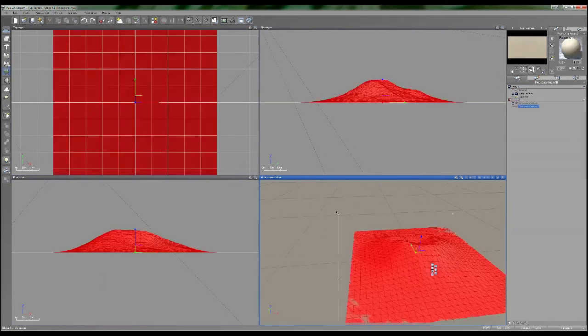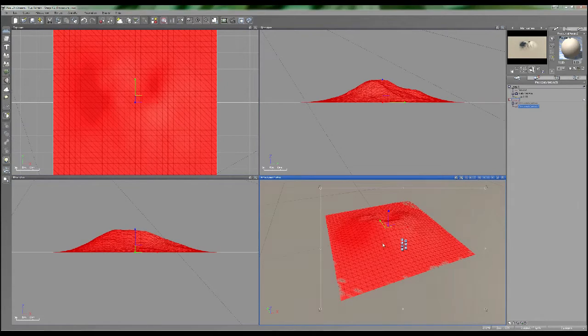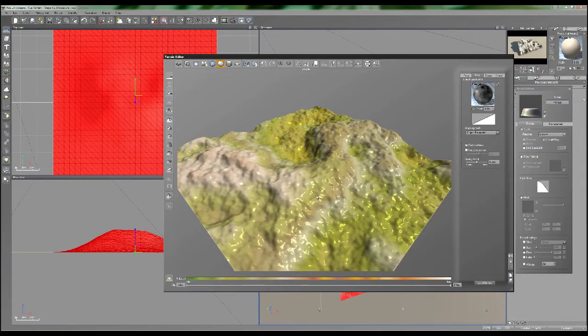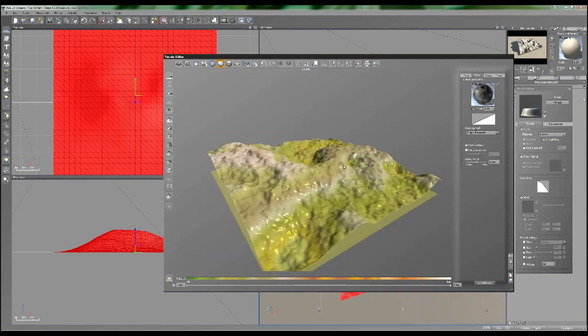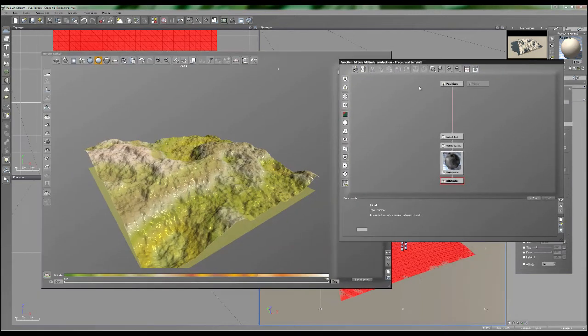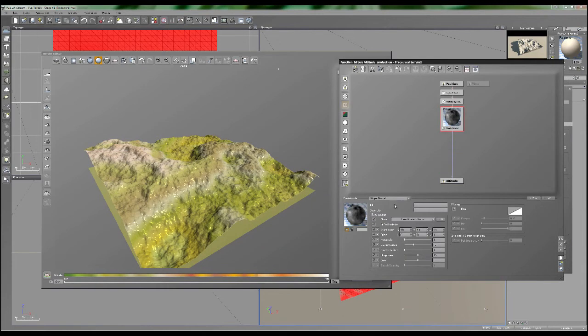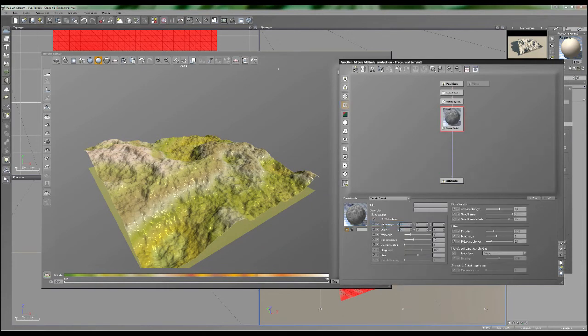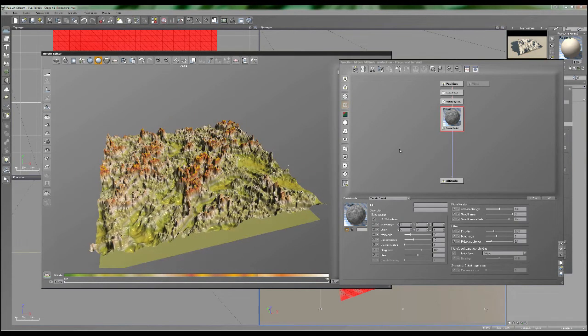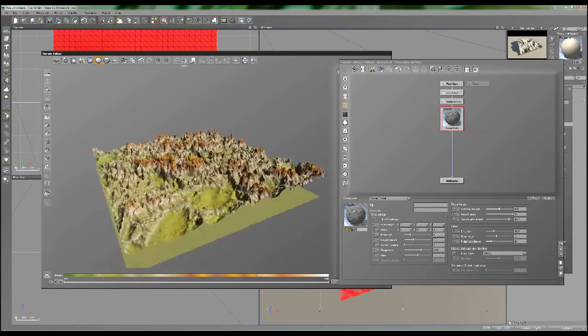So over on the left, click on the procedural terrain. We just double click on it to grab this, turn off the zeroed edges so we get a nice continuous terrain. I'm just going to turn up the details one before I go and edit the function. Let's arrange these windows here so we can see them both. We'll change the fractal that's there to a terrain fractal, and this can be whatever you really desire, and that's actually pretty close to what I'd like, just to start with.